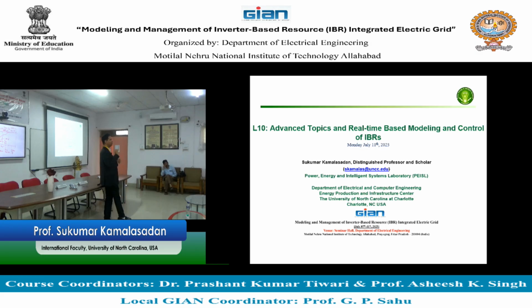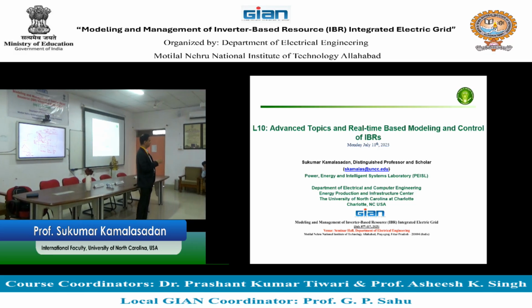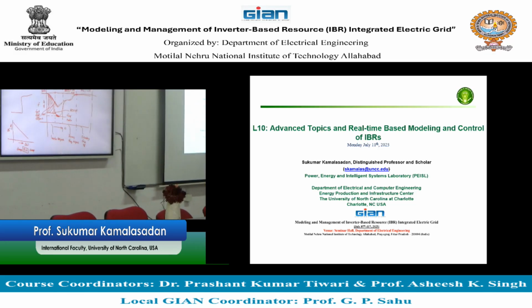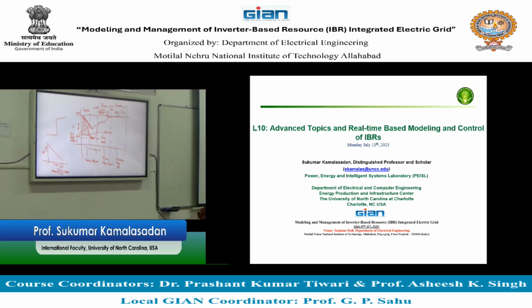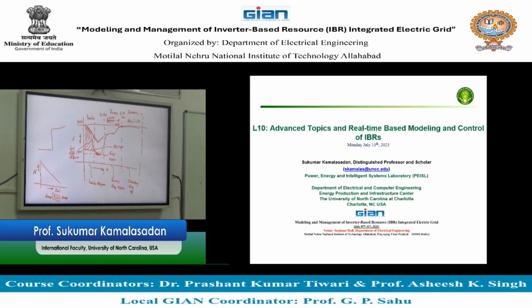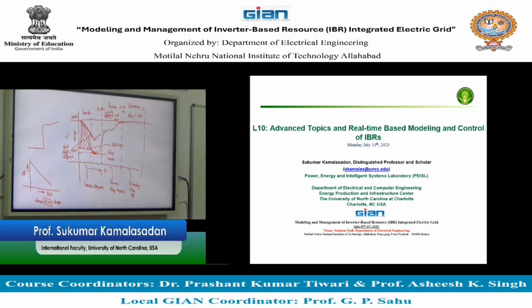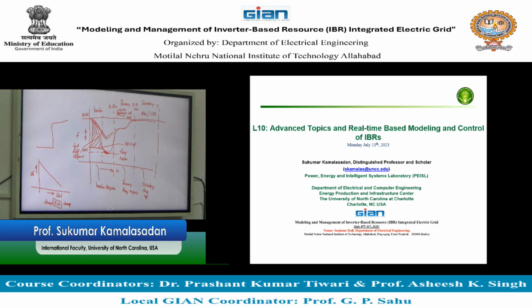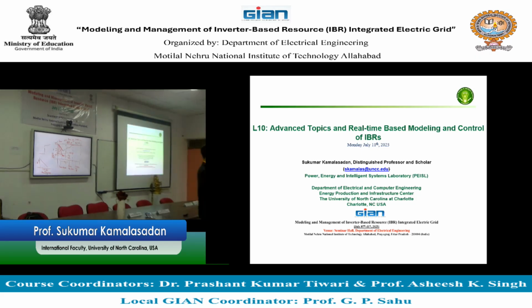So in the controller, if you want to take 1 minute to refresh, we say that the inverter is the front end. Inverter is connected to the grid. Inverter connects to the grid through this controller. And to connect to the grid and deliver what the grid requires, if the grid is available, the inverter needs the frequency of the grid, the angle that is working from the grid, and the power that the grid wants to deliver. These are the only three you need.